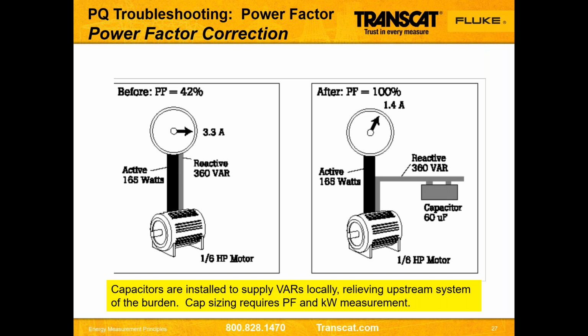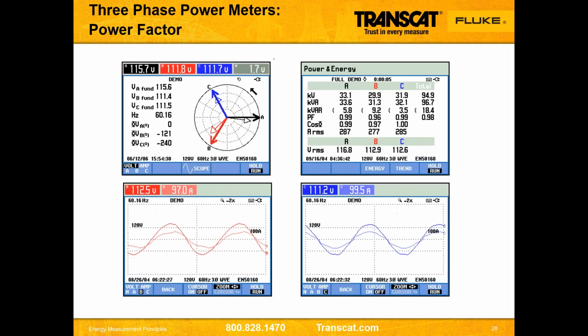So we've replaced them now with electronic loads. Unfortunately, the new electronic lighting, such as CFLs or LEDs, or electronic lighting controls, can actually produce a lower power factor now. So we want to quantify. We want to go measure. We want to go look and see what individual loads are using. And then based on that, I can come up with a game plan where I can go investigate a more efficient device and replace the older one that's less efficient with the newer one that is more efficient, and have it pay for itself based on energy savings. And this is a lot of how you can use a power meter.